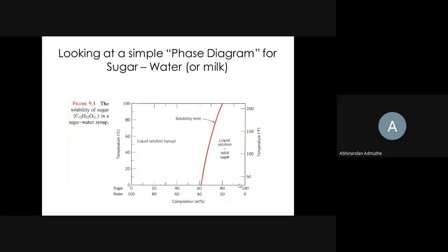All the phase diagrams which exist in nature show the same typical template: two vertical axes for temperature, one pure water, another pure sugar, and a horizontal axis where the percentage of solute, or sugar, continuously increases from 0 to 100, left to right. Now, this is a sugar water system.